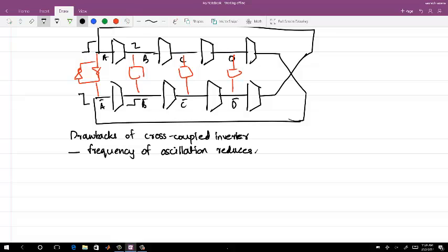But the signal coming from this is delayed compared to what would be coming from here. So you will be fighting against some other circuit block which is resisting you from making the change. With delay it will come, it will assist in both ways, but there is an added delay. So the frequency of oscillation actually goes down, in addition to the loading you have introduced. Does that make clear what happens when you put these cross coupled inverters?